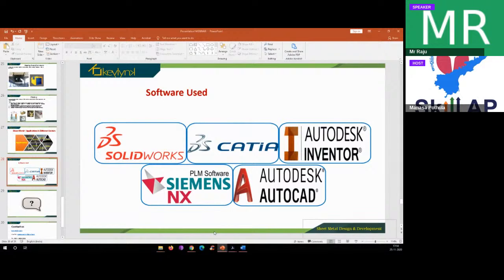and at the machine shop or the industry, they take the drawings and they will go on with the necessary manufacturing with the help of the sheet metal, using dies, punches, and all the necessary sheet metal operations, and they'll prepare the model using the operations. And after the sheet metal operations are finished, if any impurities are there, they are taken out using the acid bath or the grinding tools. If any joining processes are there, we use necessary joining processes like welding, riveting, all those things.